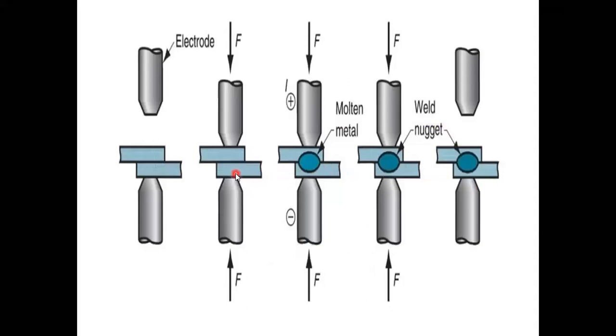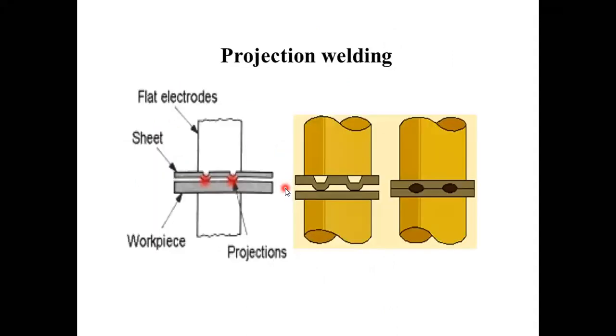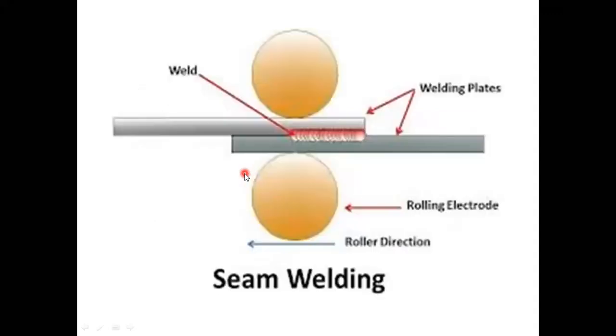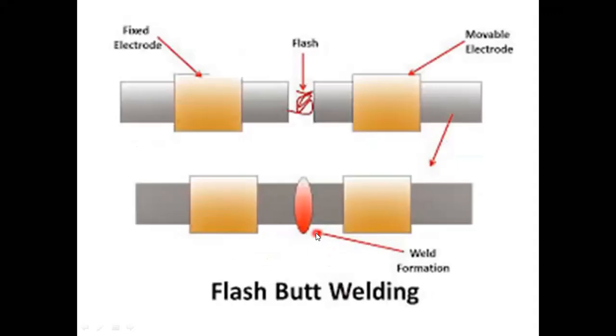Look, spot welding is applied for pinpoint joining, where joining is required only for the spot. So where I want to join only a small area, we use spot joining. Where we want to join two or three specific places, we can use projection welding. And whenever we want to join throughout the line, and the joining should be more robust than spot and projection joining, then we have to apply seam welding.